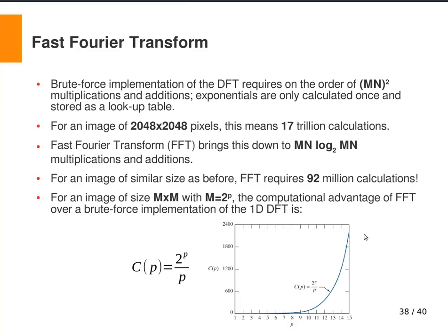If you remember, to center the Fourier transform we had to multiply all the individual pixels with the function (-1)^(x+y), but the equivalent in MATLAB is FFTSHIFT and IFFTSHIFT. FFTSHIFT centers the Fourier transform, and IFFTSHIFT brings the centered Fourier transform back to its original location.